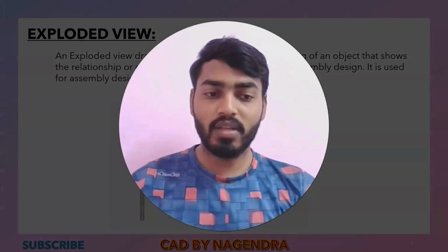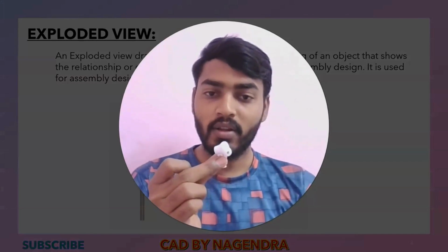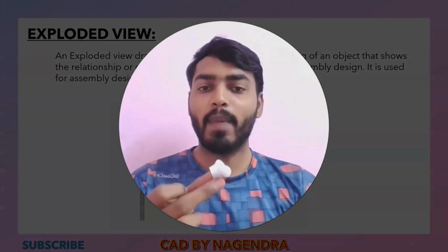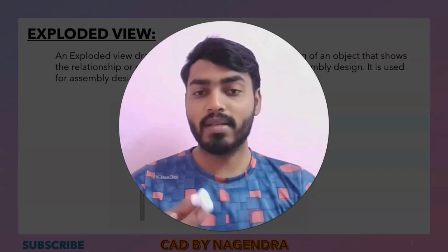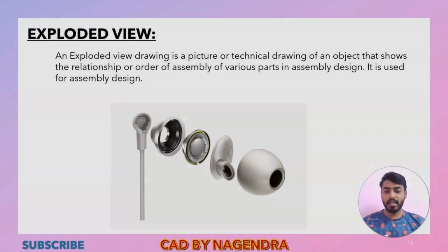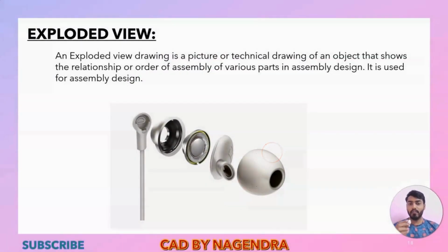Let's say we have one earbud here. Inside we will have many parts, but we don't know how many parts there are and which part is assembled to which one. So in such cases, we make this assembled part exploded, and we are able to see in total how many parts there are, which part is assembled to which one, and where exactly it is assembled, by using this exploded view. Usually the exploded view is used for assembly designs.